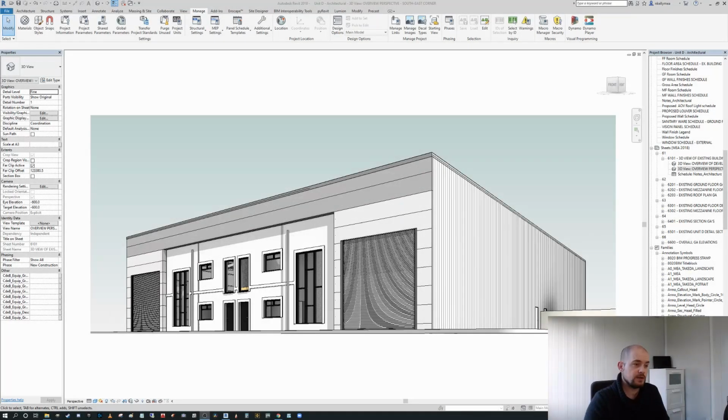Step 1. How to select an element within Revit through the element ID function. Every element within Revit, be it a family or an in-place family or profile, is automatically given an element ID. An element ID is basically a way of identifying an element within the overall project structure, from an information perspective.